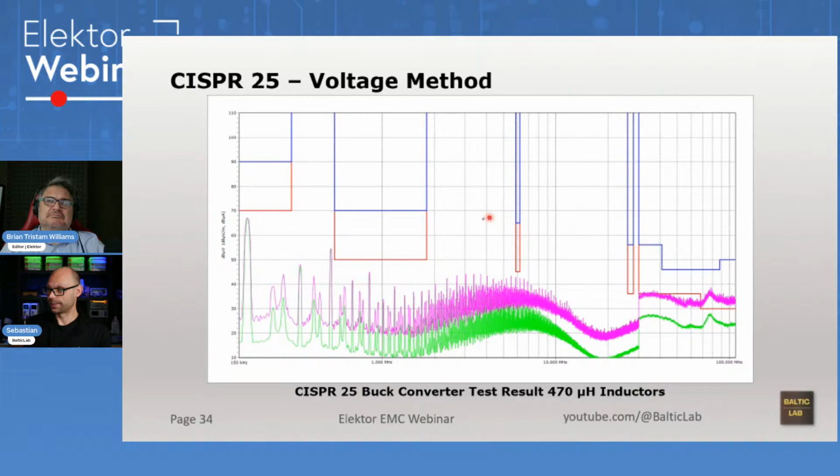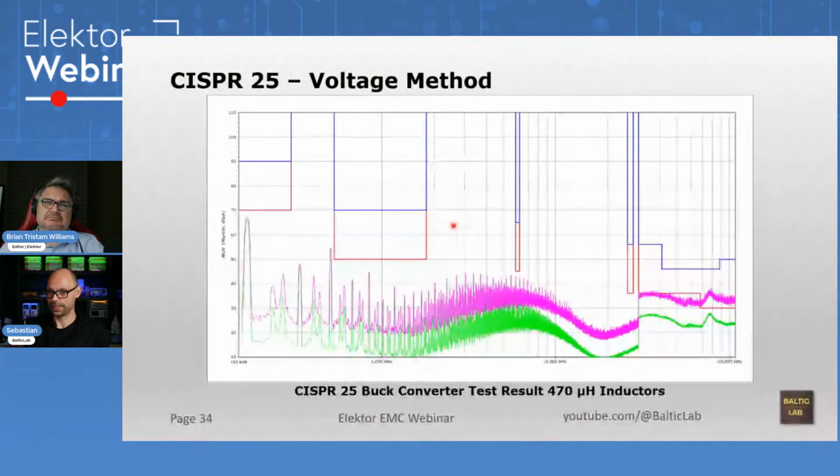Remeasuring, these are still CISPR 25 Class 3 limits. And look at that. That's all we need. Like I said, it's a shame because I was kind of hopeful that I needed higher order filters, but I don't. That's it. Problem solved. Now we can go for compliance testing.